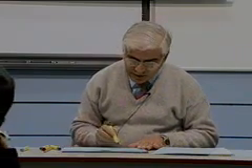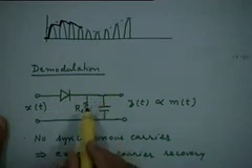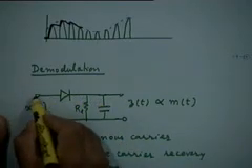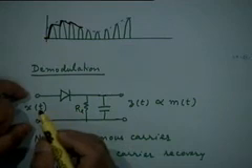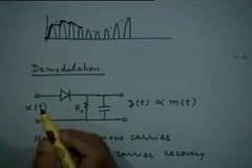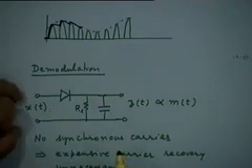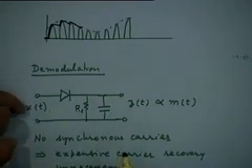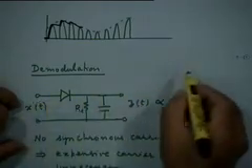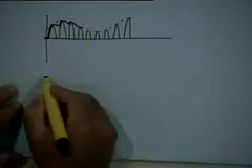Now for this to work, are there any conditions that you should satisfy? Obviously yes. Let's look at the charging path. The charging path is through, let us say, some source resistance that you might associate with the input. After all, the input is a voltage source coming from somewhere, maybe from an antenna or from some amplifier stage previous to the demodulator, right? So there would be a source resistance associated with the waveform x of t. Let's say the source resistance is R sub s.